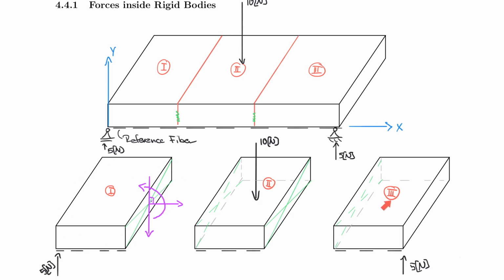The next easier one is probably the part 3 here. So the system 3, let's put that into equilibrium. And yes, you guessed it, we of course need a shear force, a normal force, and a bending moment as well. So let's introduce those forces too. We need a vertical resistance in the glue. We need a horizontal resistance in the glue. Again, these two are perpendicular to each other. And we need a moment that is strange to see in this case, but we need something that prevents bending as well. And right now, I'm not really concerned about the direction.